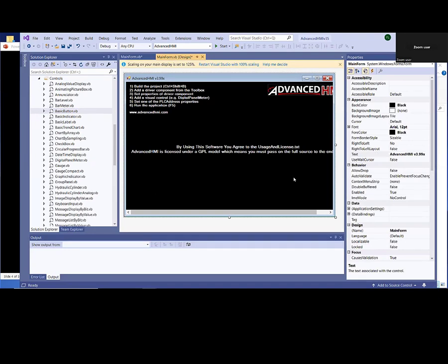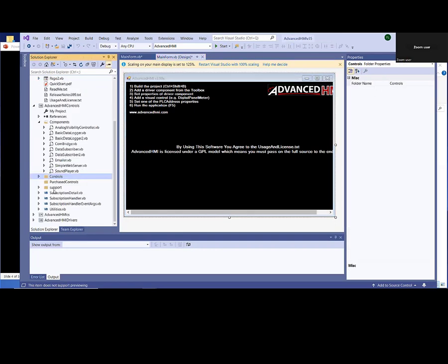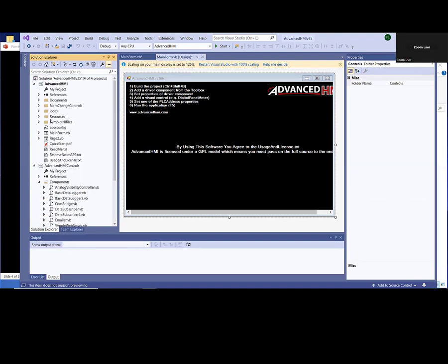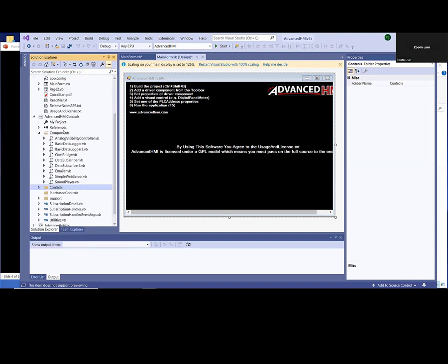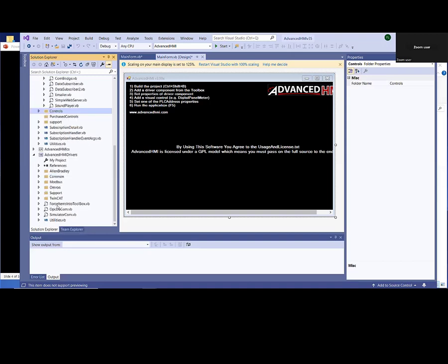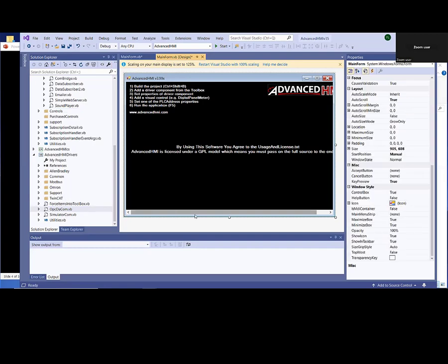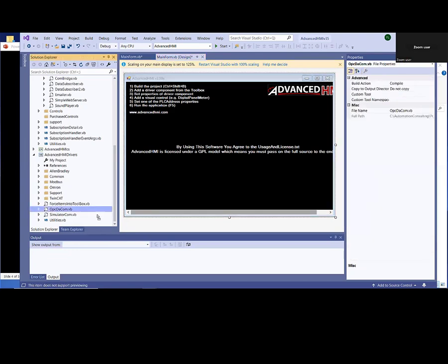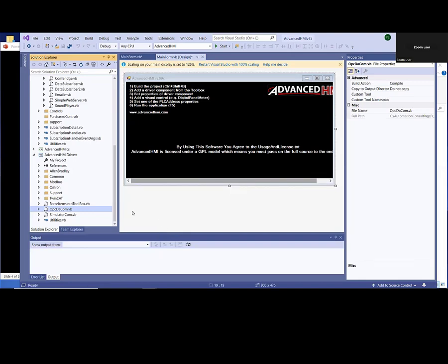Oh, well, before we do that, the other thing that you need to do is say, well, what am I going to talk to, right? What PLC do I want to talk to here? So in this case, I want to go to the drivers folder, and that's where that little widget I showed you before showed up. And in my case, I was using the OPC driver, and I drag it onto the form. Should have shown it. Done this before, and it just dragged it right in.